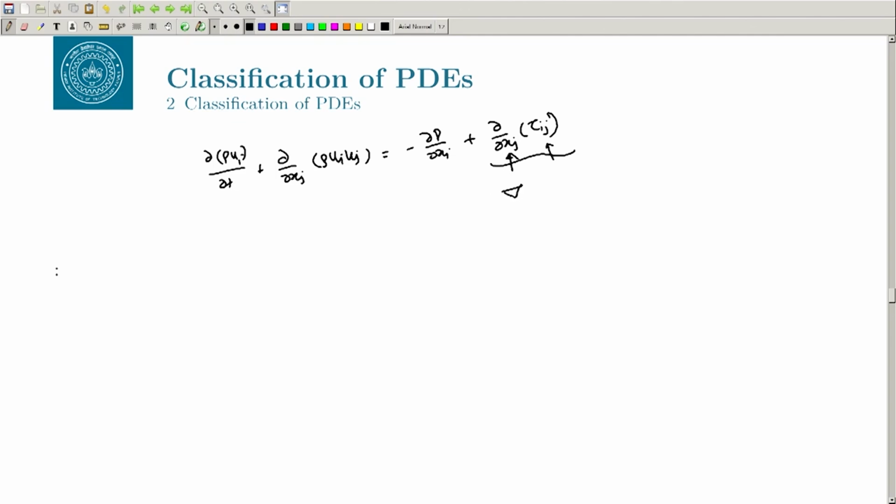So, for example, in incompressible flow it is exactly like this, del square u into nu, right, and even on the compressible side it will be like mu, okay, it will be 2 mu E_ij, del by del x_j, and minus 2 by 3 mu delta_ij del u_k by del x_k, right.